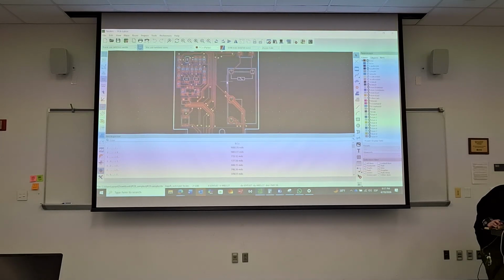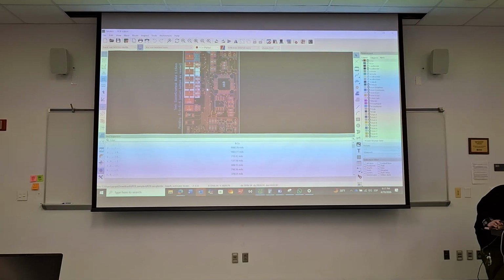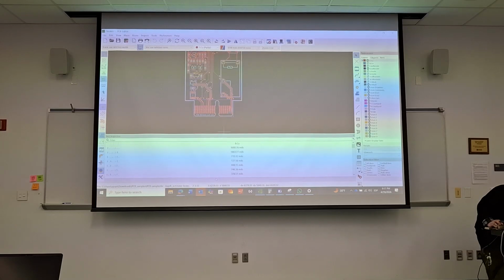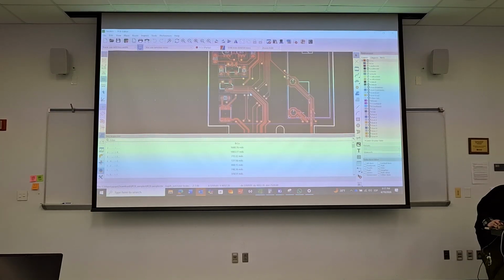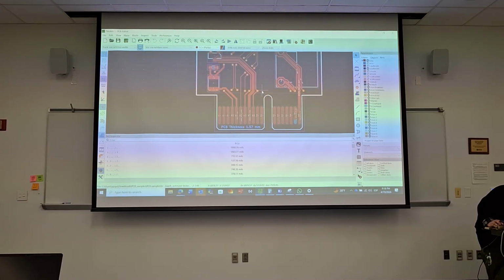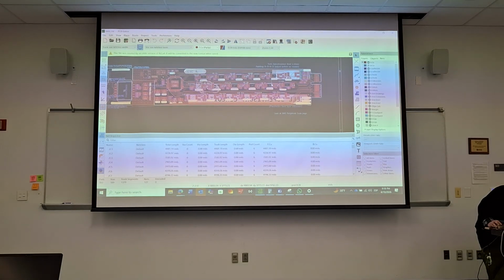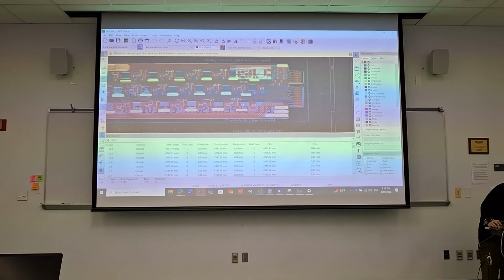It's worth another revision. I would at least add some layers for better grounding. That's where I would start. Also, this antenna is not great. It's, wow. Yeah. Because this is at least terminated here, but this isn't. Yeah, start with that. This one, geez. This one's actually fine, because this is what this board did right.